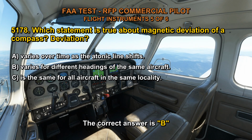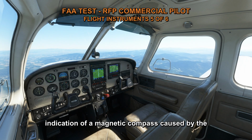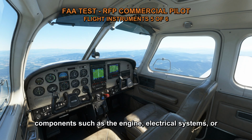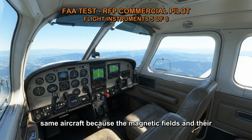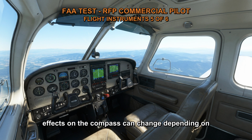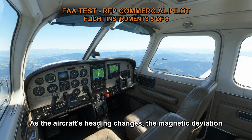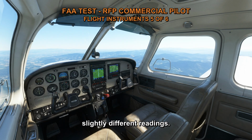The correct answer is B. Magnetic deviation refers to the error in the indication of a magnetic compass caused by the magnetic fields within the aircraft itself. These magnetic fields can be generated by various components such as the engine, electrical systems, or ferrous materials on board. Deviation can vary for different headings of the same aircraft because the magnetic fields and their effects on the compass can change depending on the orientation of the aircraft relative to the Earth's magnetic field. As the aircraft's heading changes, the magnetic deviation can also change, causing the compass to provide slightly different readings.